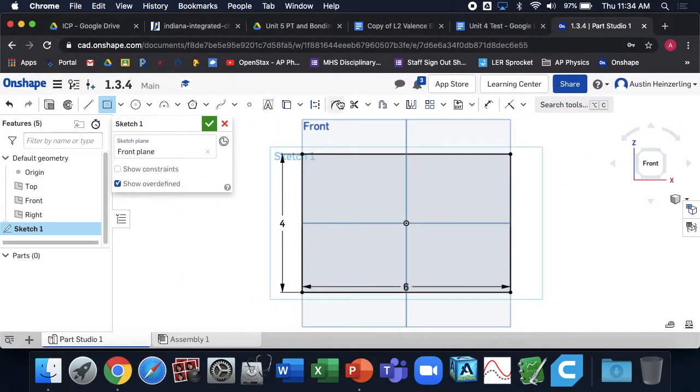There's 2 ways that you can do that. This button right here will switch your drawing to be construction lines, these ghost lines. And I can say I want to draw a line from corner to corner. Do you see how it's dashed? That tells you it's a construction line. It won't actually impact the shape that you're drawing. Then I want to draw another one, corner to corner.